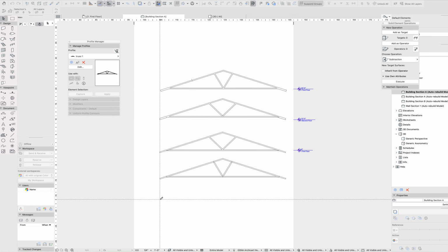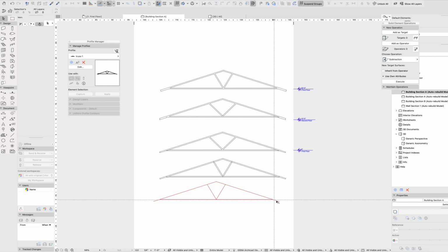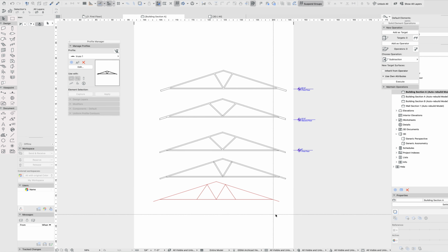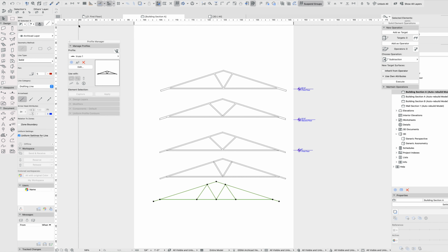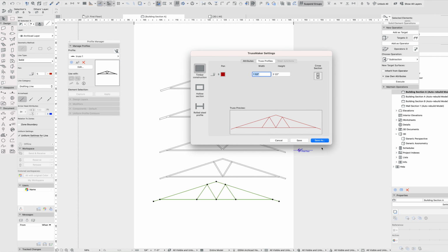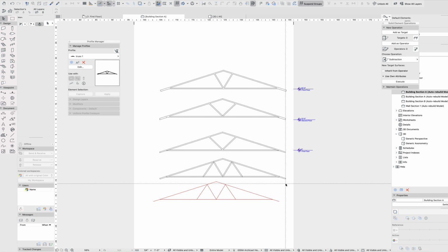Continue editing. And then I can actually edit the elements that were used to generate that truss. So you don't have to necessarily hang on to that line work. I can then go back in and add stuff back in if that truss needed to be something different. And from there I can essentially redo the same thing. The only thing that edit truss does is it allows you to avoid having to redraft, retrace that, so you can go back through and create a new truss from that. Overwrite it, and it should update in every instance. So if you do need to make a change, you can make a change using the edit truss.